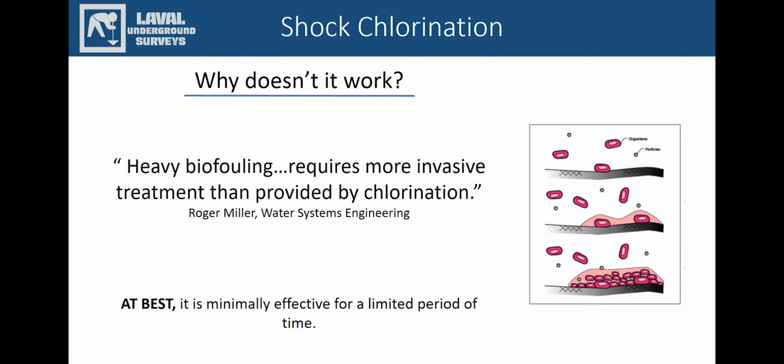Iron-related bacteria and sulfate-reducing bacteria are coated in thick layers and are protected by their slime. Shock chlorination may kill some surface-level cells, but the rest are left untouched. Chlorine removes extracellular polymers and not biofilm cells, leaving biofilm cells more exposed to the nutrients, which is the oxygen in the water, once the cleaning is finished. Their surviving cells rapidly create more slime as a protective response to irritation by chlorine. Iron dissolved in the water may also absorb the disinfectant before it reaches the bacterial fouling, basically rendering it useless.